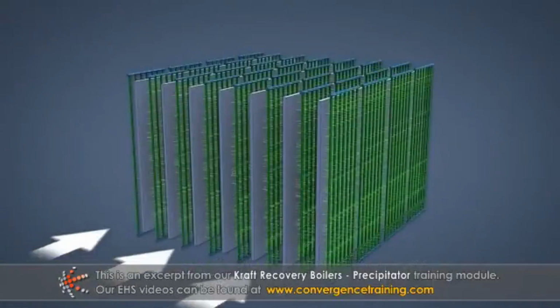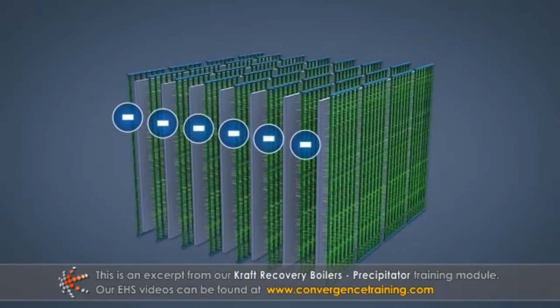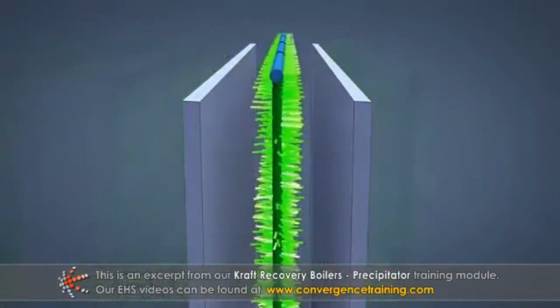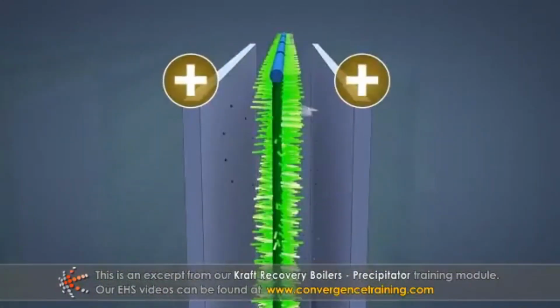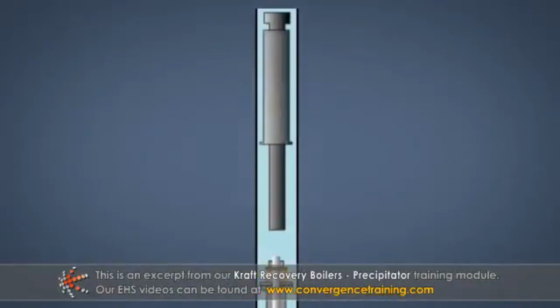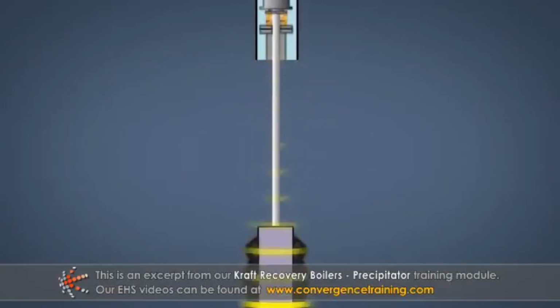As the exhaust gas passes between the plates, high voltage applied to the electrodes causes the particulate in the gas stream to become negatively charged. The negatively charged particulate is attracted to the positively charged plates and is collected on the plates. Rappers shake loose particulate from the plates, which falls into collection hoppers for removal.